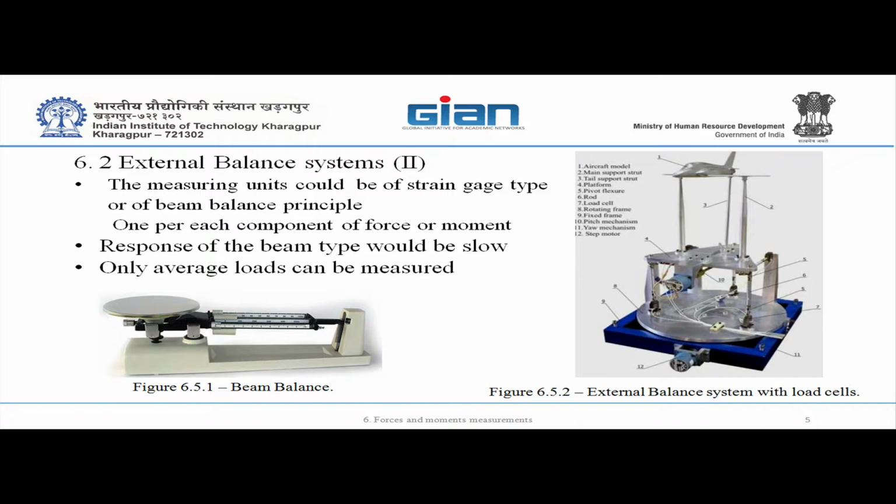So they connect a sting balance capability to the rotating table, to the balance. They use the struts to hold the sting balance. So the aircraft is sitting ahead, no disturbances, and you measure with the sting balance, high frequency, no problem, and if you want, you even get a redundancy result. So instead of replacing the whole system and trying calibrating, the big headache, they just replace it with a sting balance. The problem is, if you come with a big aircraft,